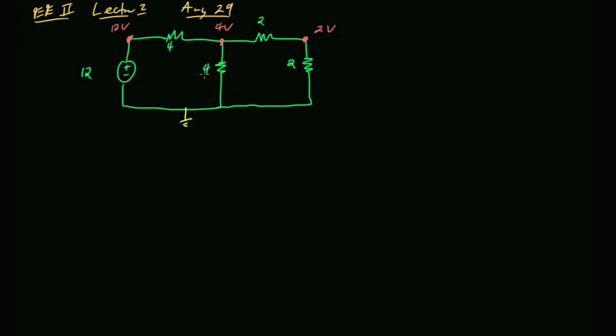So really, if I decrease any one of those resistors, should it matter which one I decrease? No, right? If I decrease any resistor, the net impedance that the power supply sees will go down, which means that current will go up, which means that power will go up. Pretty cool, right? So I wanted to do a couple more intuitive questions here.